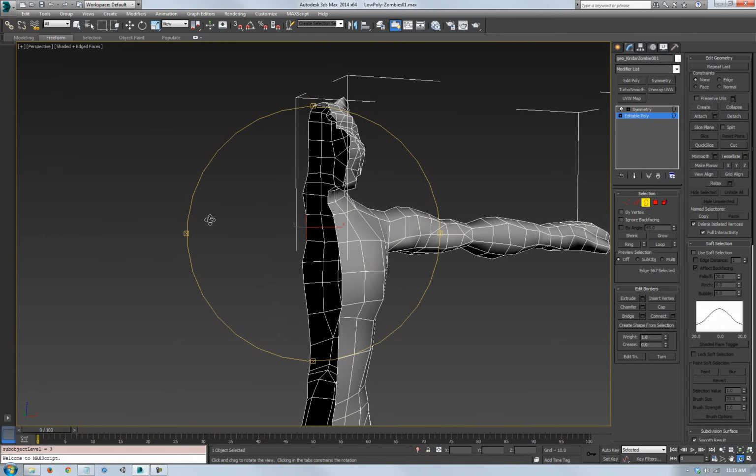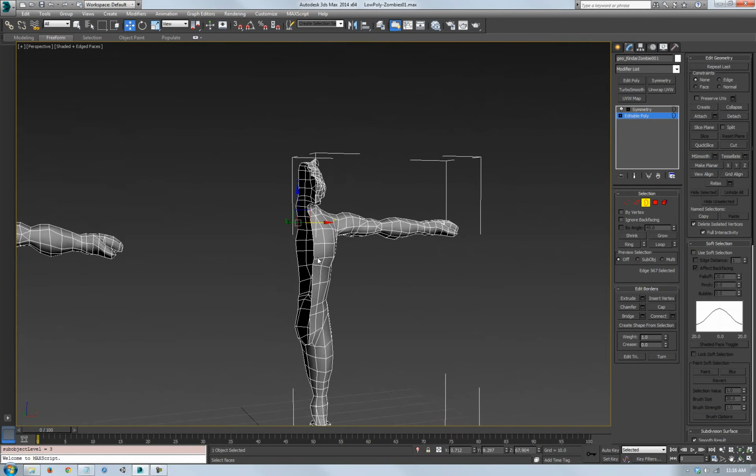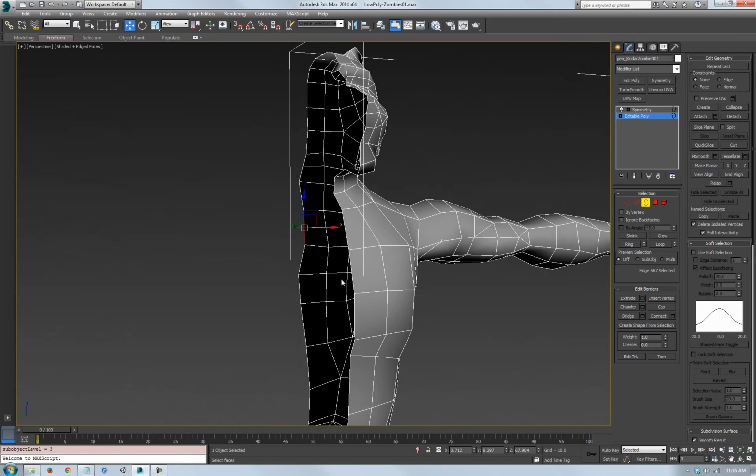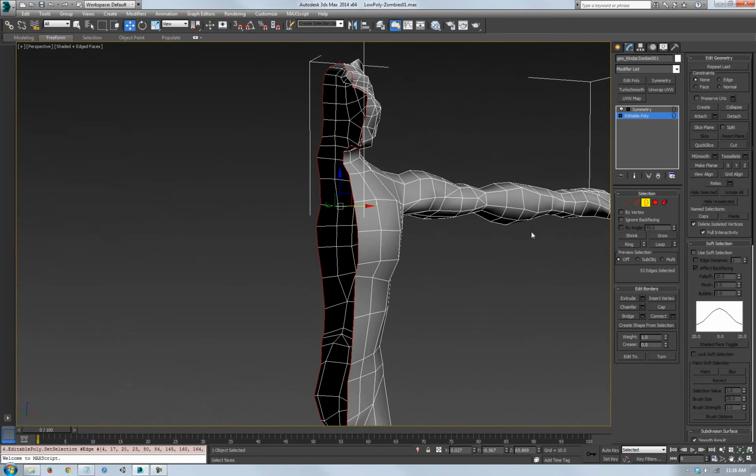Now, how do I usually fix this if I've got it? This is going to be a quick and dirty fix. I just go into the border. This is assuming that I'm on the 0 world point, because this is only really useful if you are, because I'll show you how it can muck things up. So I then use the border, and I tell it to select the inside border, which is from the crotch up the back, up the neck, and the head, and down the front.